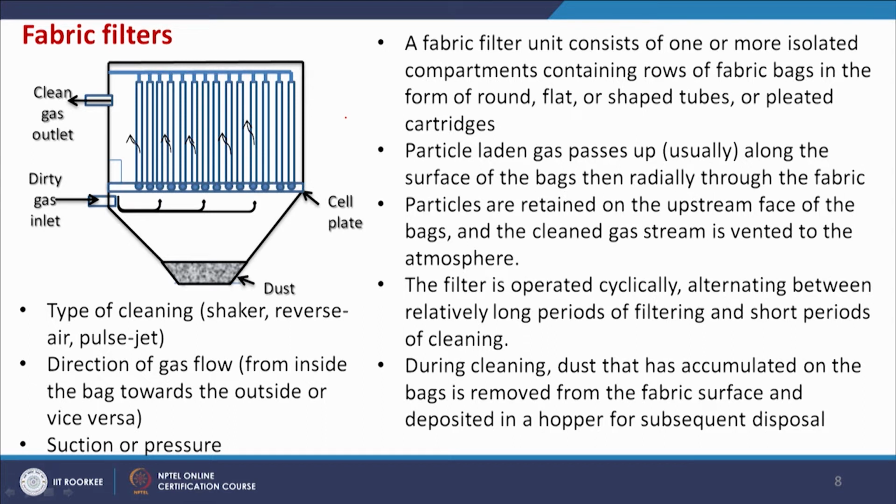So, you see this figure shows us the operation of fabric filters. Here this is our dirty gas, it is coming in, and there are a number of cages, and each cage is covered by the fabrics or the bags. The particulate matter laden gas is coming here, and it will be passing through the fabrics. Basically there is one blower at the top, so some suction is there, and the gas which is coming will be forced to go through the pores of it.